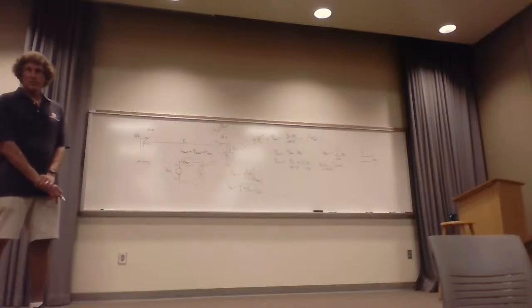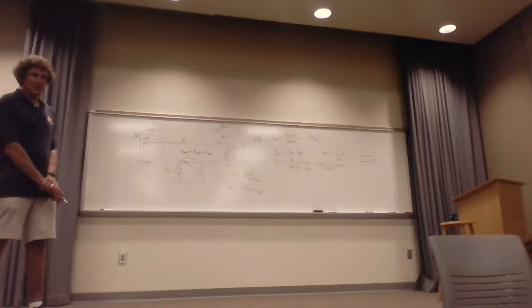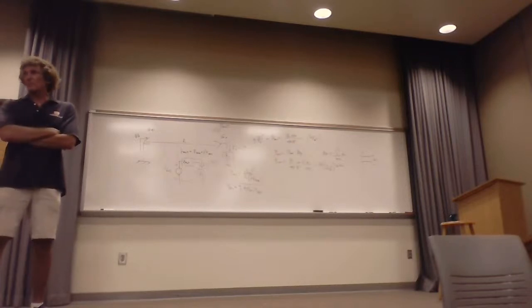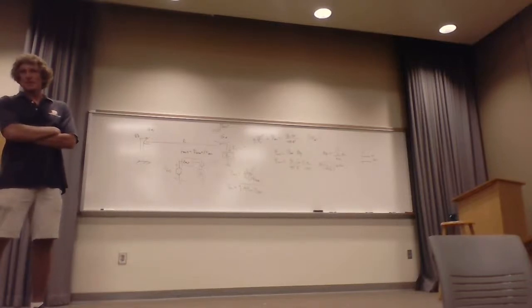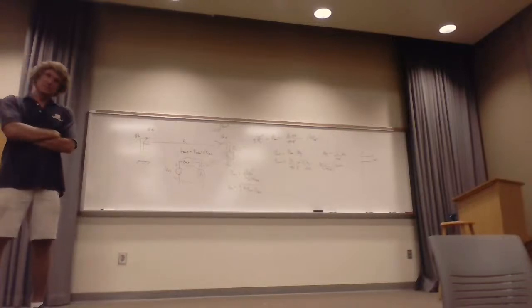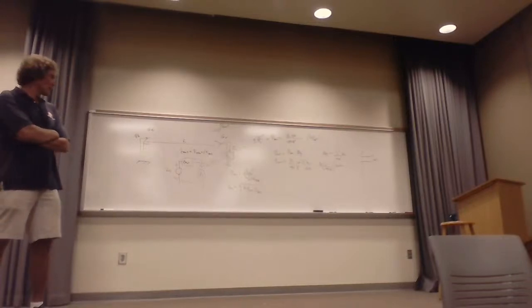For the half-wave dipole, I'll give you the gain of that, the 1.64 times the cosine of pi over 2 cosine theta over sine theta, because you guys might mess that up, and that's understandable. I mean, the basic equations you should know, like the stuff we're going over right there.